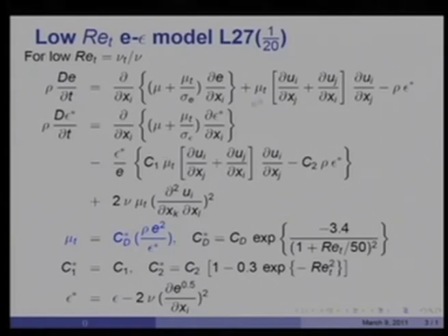Then there are the turbulent production terms and the dissipation term of the modified dissipation, and likewise here also. But the constants now are changed, and are sensitized to distance to low turbulence Reynolds number regions. So, for example, one such term which is sensitized to distance from the wall and low turbulence Reynolds number region is 2 nu mu_t (d²u_i/dx_l²). The reference to all this will appear shortly after a few slides.